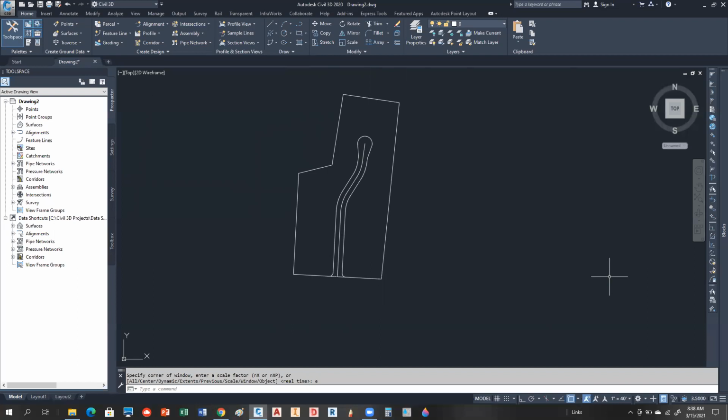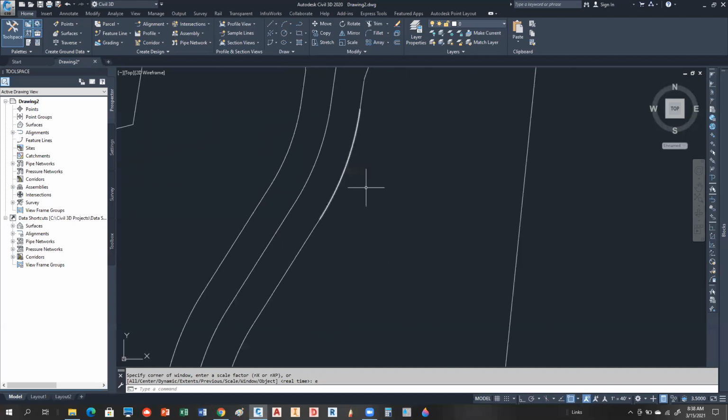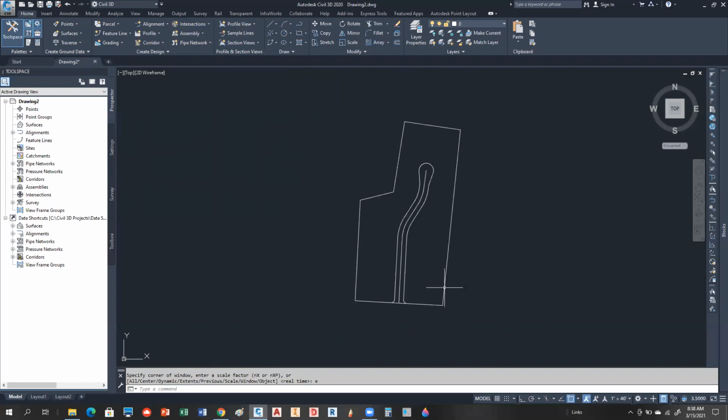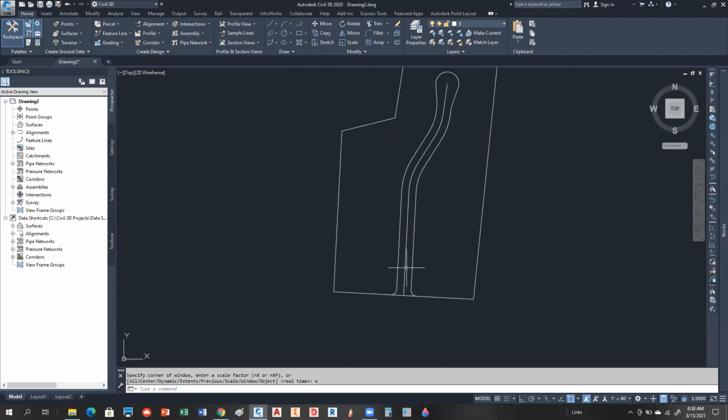Well, okay, so here's the important thing now. We kind of got the stage set for doing parcels, and you have to make sure that all of this stuff works. You can't have holes anywhere. So you have to think, I've got a closed polygon here. I have an external closed polygon, and then this is going to be another, like, internal closed polygon. Okay, so that's the important process. And that's kind of why I was doing it the way I was doing it. So if parcels fail when you try to execute them, that's a lot of your problems, particularly.